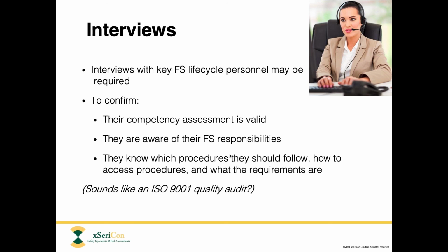Second point would be to make sure that they're aware of what functional safety is and what their responsibility within the life cycle is. The reason for asking this question is we very often find the case where the functional safety management plan is just a huge document gathering dust on a shelf. And it says person X is responsible for task Y, but person X doesn't even know that because they've never been informed. So we want to make sure they've actually been properly informed, and they have the knowledge, they have the training, and they have the resources to execute those responsibilities.